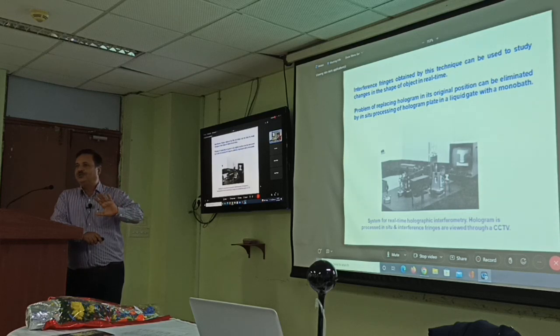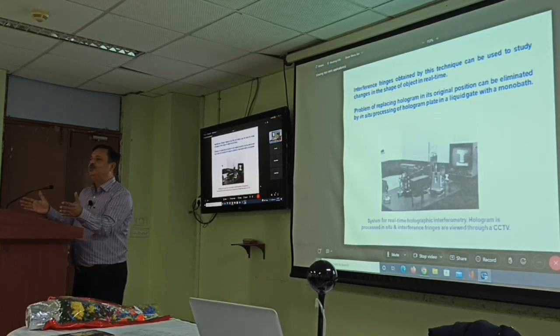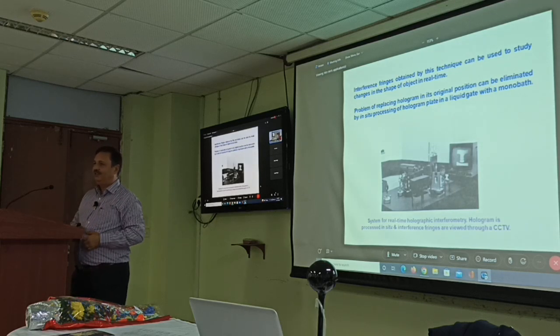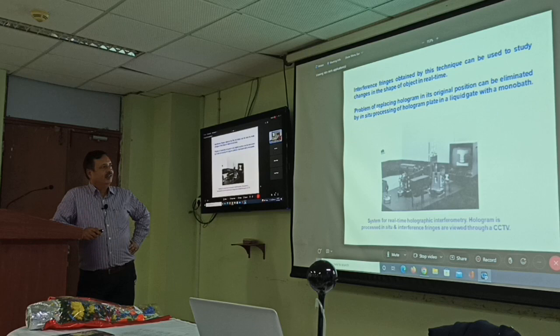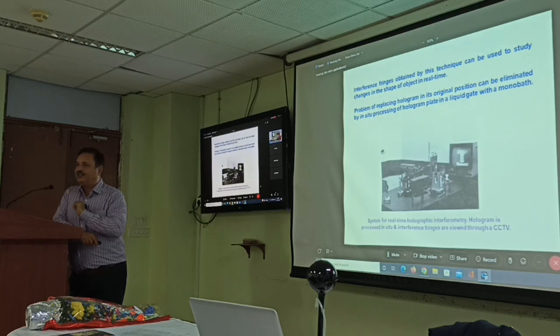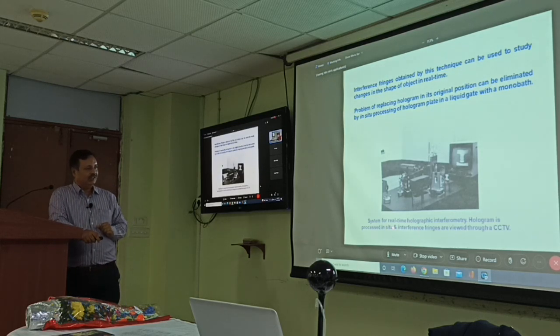So one change I showed, that deformation has happened. Any such changes can be observed. So basically the simple thing is, you are comparing two interference patterns or two holograms. Because the first hologram has the information from the original position, and the second one is with the deformation. So how much the deformation is, that we can measure. And this is a setup. Now here is the problem, that you have to replace that hologram in its original position, and then you have to record another hologram. So that posed a very difficult problem.